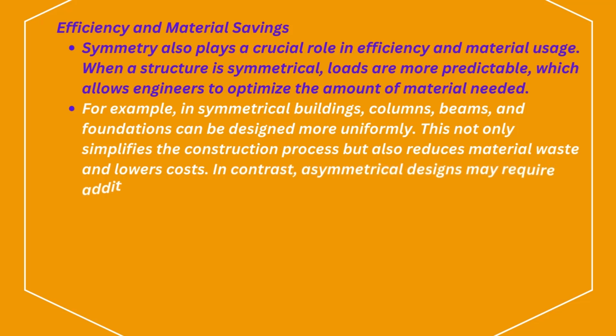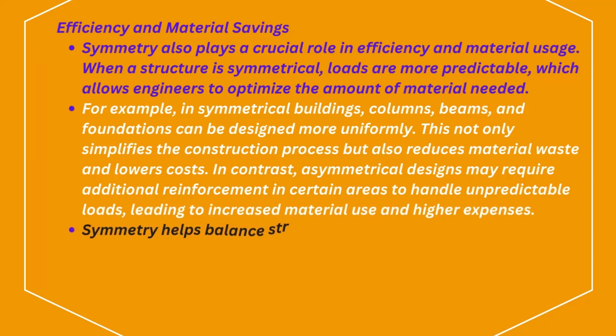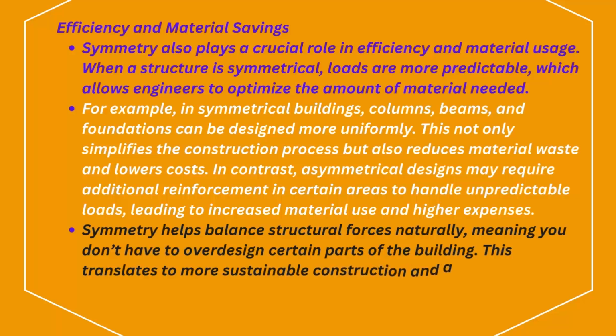In contrast, asymmetrical designs may require additional reinforcement in certain areas to handle unpredictable loads, leading to increased material use and higher expenses. Symmetry helps balance structural forces naturally, meaning you don't have to over-design certain parts of the building. This translates to more sustainable construction and a more efficient use of resources.